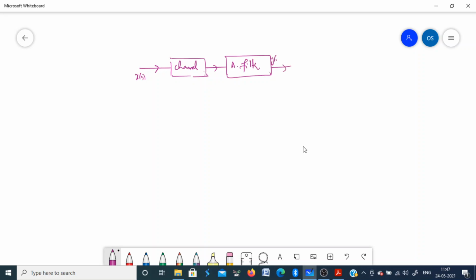Okay, yn, and then you have a desired response here, dn. So you have some error signal en, feedback to this adaptive algorithm, update the filter weights. So if you apply some input to this channel, and this dn, which is the desired response, this is basically same as the input to the channel.